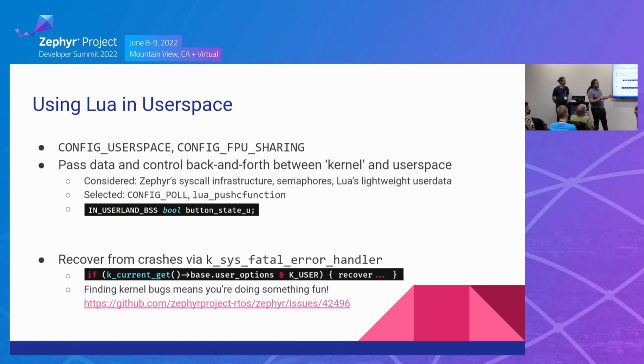And then when we call that periodic function and we retrieve its Lua return value, and then in C we interpret that and do some write to a similar piece of memory that when we yield back to the kernel by triggering this poll, that's going to get read and get bounds checked and get duty cycle checked and check against whatever safety configuration parameters the user has installed.